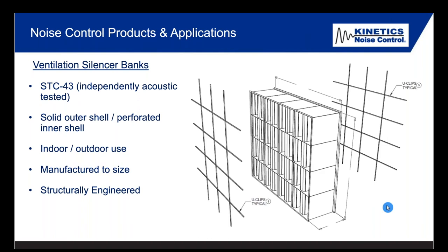And then if it's a large bank of silencers, we can do that as well, but not just sell you a bill of goods that might be small building blocks of silencers, but also help you, depending on the width and height of this. Sometimes these can be 20 foot tall and 40 feet wide. We help you determine the added structural steel you may need as backer structural, because even though these have holes in them, what I've always been told by our structural team is you still have to basically, per IBC, in most parts of the country, you can't give any credit to those holes. You have to treat it like a solid barrier. So it has to have the backing strength.